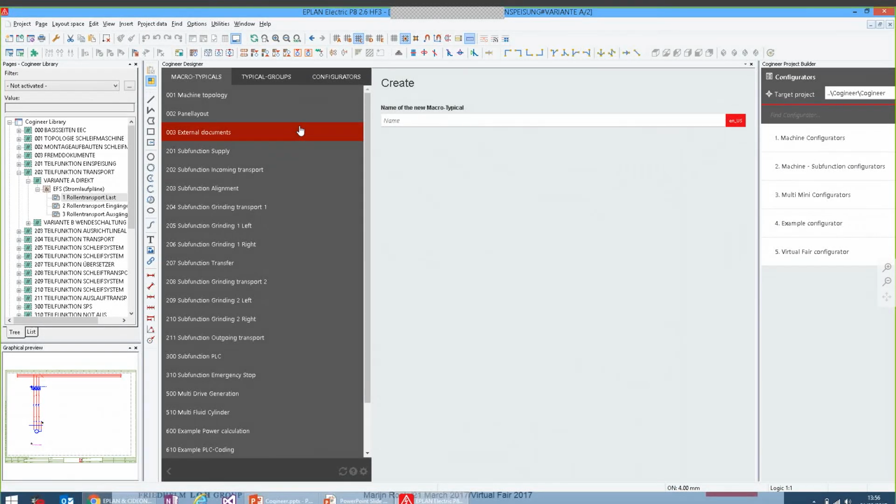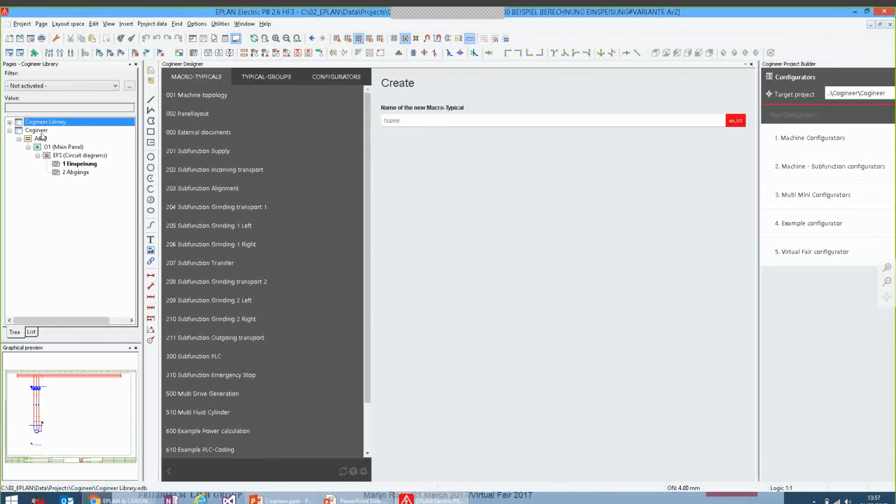It's no problem. Will it be available in EPLAN 2.5? No. At the moment, it's created from version 2.6. Do I need a base project for the macros? No, you just need a library, and this library is actually a macro project. And you have to have a macro project to start. But very easy. If you have this, I can show you very quickly.